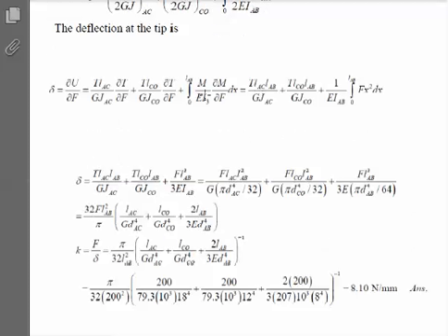Doing this integral, moment written in terms of F, the moment was F times X, and then the partial was another X. So this integral term here becomes an FX squared term, which will become an FX cubed over 3 eventually. Now just go through the algebra. This is nothing but algebra.